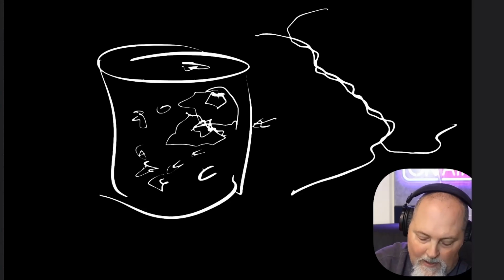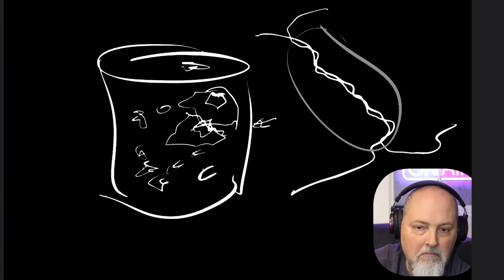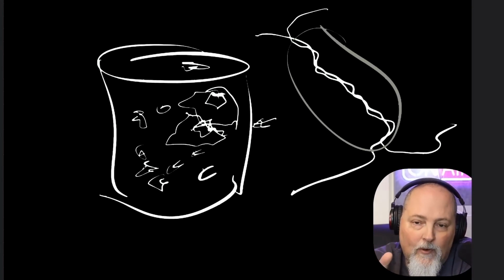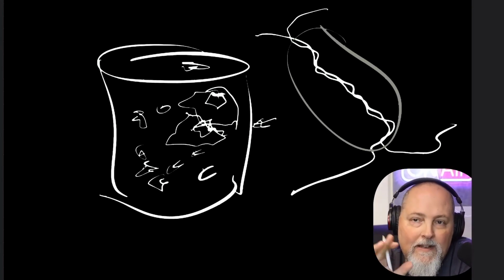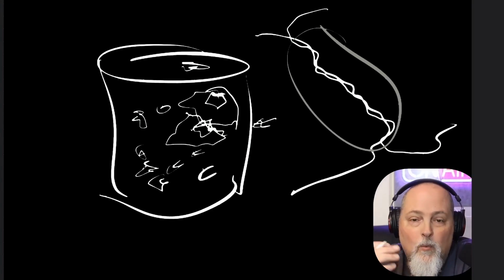And this boundary right here is the grain boundary. A grain boundary is not a crack. That's not a crack. A grain boundary is not the outside surface. A grain boundary is on the inside of the metal where two different grains oriented in different directions, two different crystalline structures, meet. So the grain boundaries matter because they affect strength and corrosion behavior. They can strengthen a material by blocking what we'll learn is called dislocation movement.